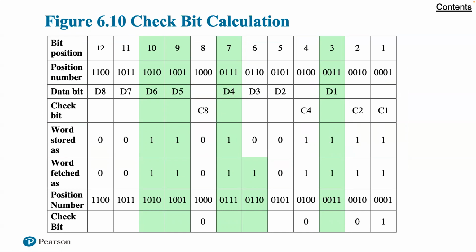So now let's look at the check bit calculation. We'll just try and give an example. Here we're trying to show an illustration of the calculations. The data and check bits are positioned properly in the 12-bit word. 4 of the data bits have a value 1, shaded in the table, and their bit position values are exclusive OR'd to produce the Hamming code 0111, which forms the 4 check digits.